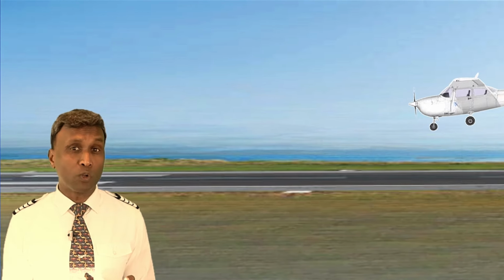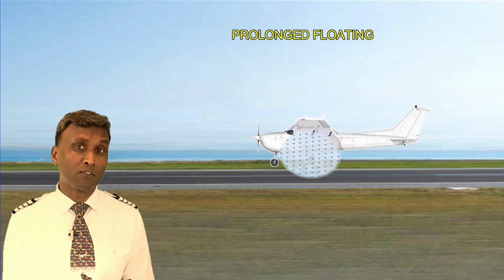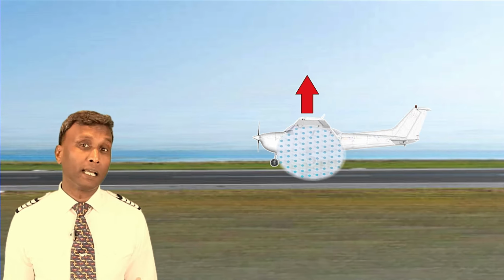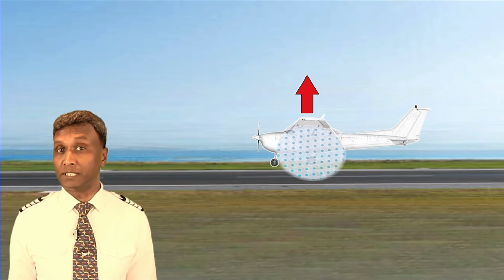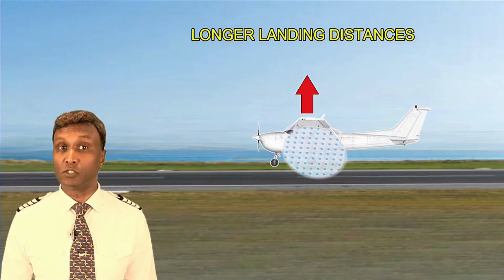Equally, pilots must also be mindful when aircraft approach at higher speeds during landing. They may experience a prolonged floating. This occurs because the increased airspeed intensifies the cushion of air beneath the wings, enhancing lift and delaying the aircraft's descent onto the runway. As a result, pilots may find it challenging to initiate a timely touchdown, potentially leading to longer floating distances before the aircraft settles onto the runway.